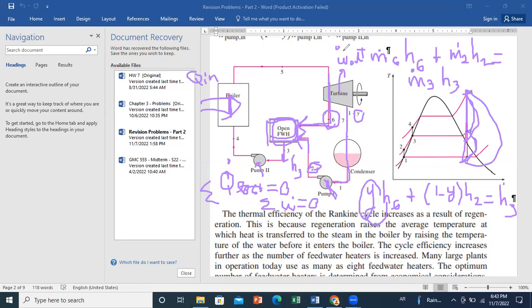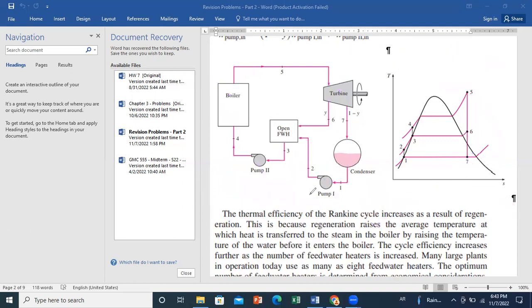And we'll be able to calculate all of these parameters, and then we can calculate the efficiency of our cycle. So let us go over an example to see numerically how we can compute the fraction y, how we can assess the efficiency of the cycle, and how we can compare by calculation the efficiency to a conventional Rankine cycle. So here, for example, once I give you P maximum and P minimum, you can compare with a conventional Rankine system and see how the implementation of the open feed water heater will enhance the efficiency of your system. Any question on the operation before we start the problem?